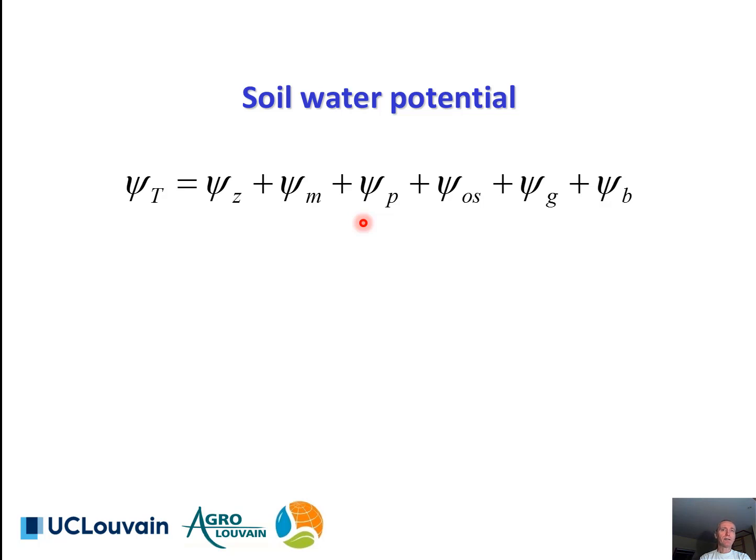If concentration gradients exist in the soil solution, then the thermodynamics of the system pushes these gradients to disappear, which results in solute transport in the soil liquid phase. This goes hand in hand with the possibility to transport water particles in the opposite direction, and hence the appearance of an osmotic force. The osmotic force results in an osmotic component of the water potential, psi-os.